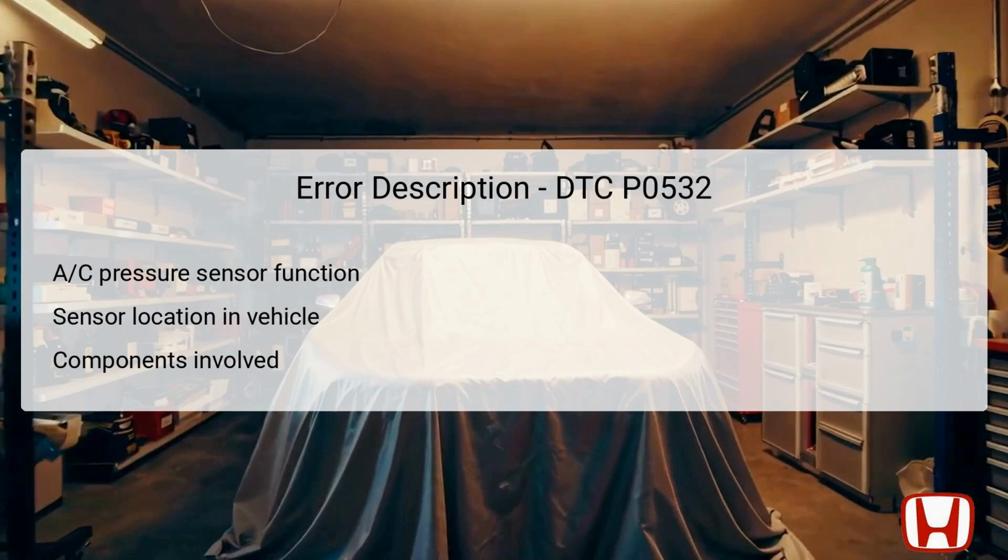The PCM interprets these signals to determine whether the AC system is functioning as intended. If the sensor outputs a voltage of 0.24 volts or less over a defined period, this prompts the storage of the DTC P0532, indicating malfunction. Understanding each component's location and function is vital to effectively diagnose and repair this issue.